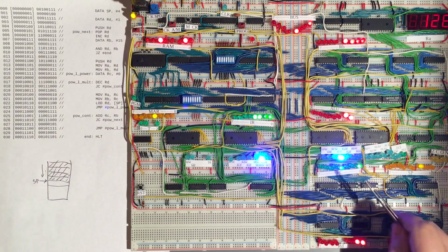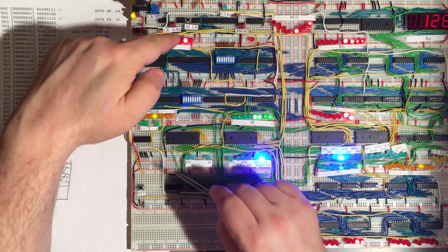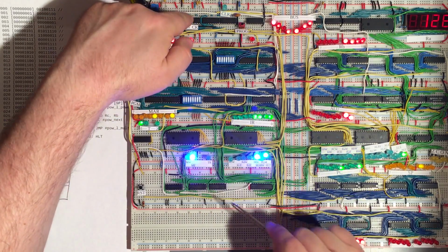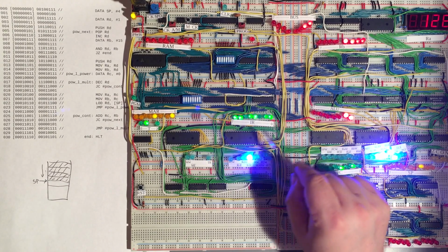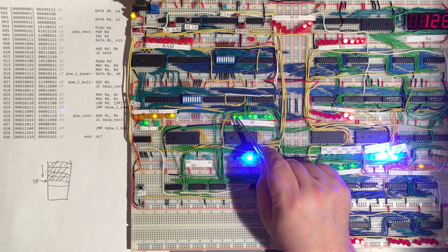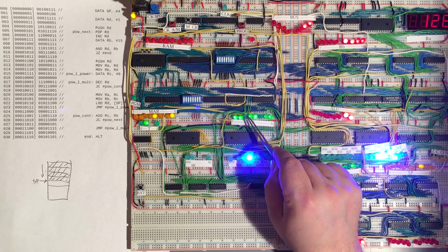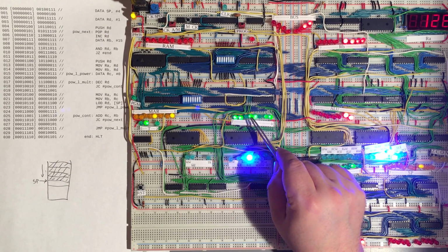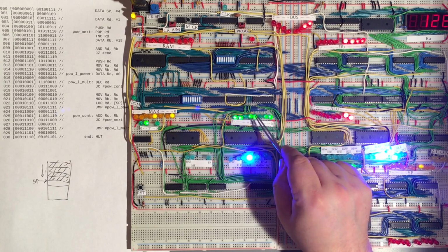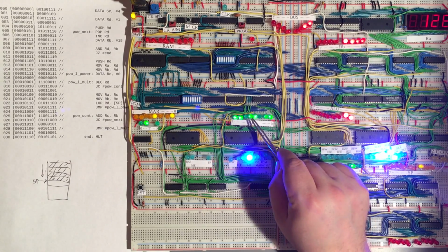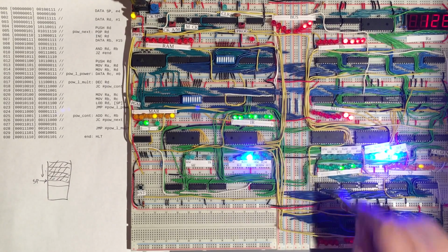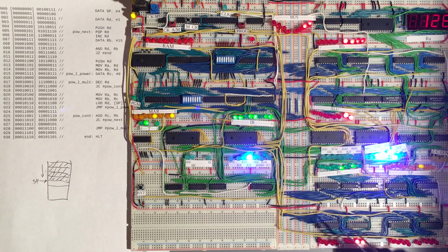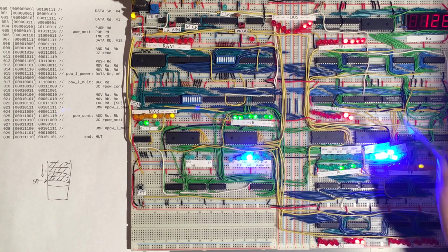So once again, let's fetch the instruction. So fetch time t0 and time t1 are always the same. Get that into the memory address register and get the instruction in here. And so our instruction is here in the instruction register now. So it's once again an ALU operation, 1-1. It's not carrying, and its operation code is 1-1-0. And so that happens to be the AND operation, and we're operating on the D register. Of course, the second operand is hard-coded to be B. So we want to calculate the AND of D and B.